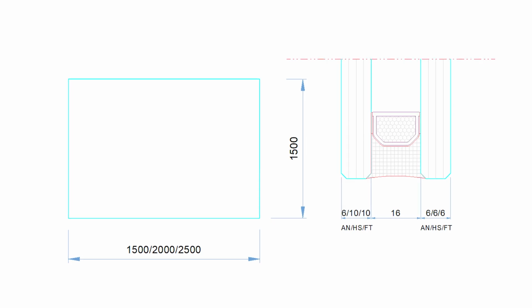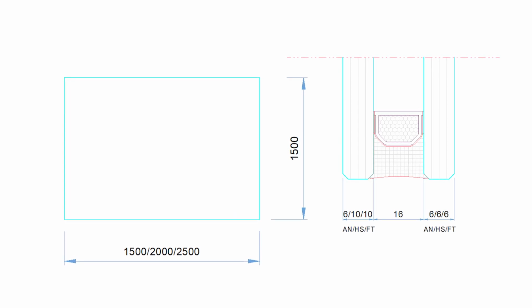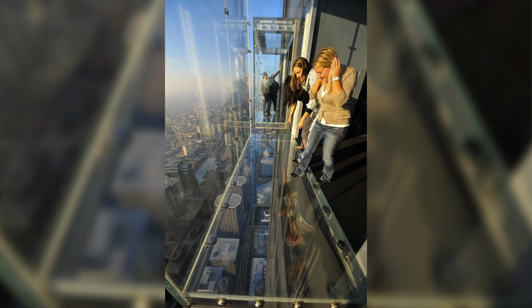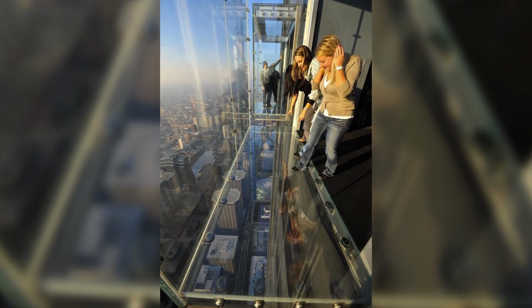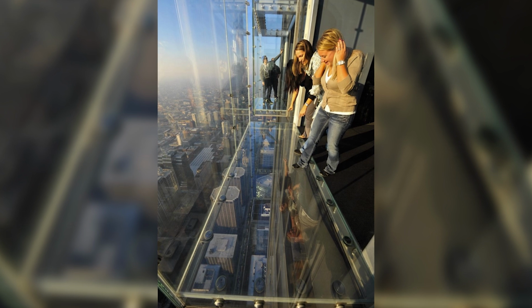The glass in the construction industry is used for many different applications with variable dimensions and compositions. For the purpose of the comparison, we have chosen the most common application: a rectangular double-glazed insulating unit, either vertical as a facade element or horizontal as a skylight element, simply supported along all edges by a frame and loaded with a lateral surface pressure of 3-second gust wind load. Horizontal specimens experience also a long-term load due to the dead load of the glass acting in the same direction as the wind load. No other loads are considered.